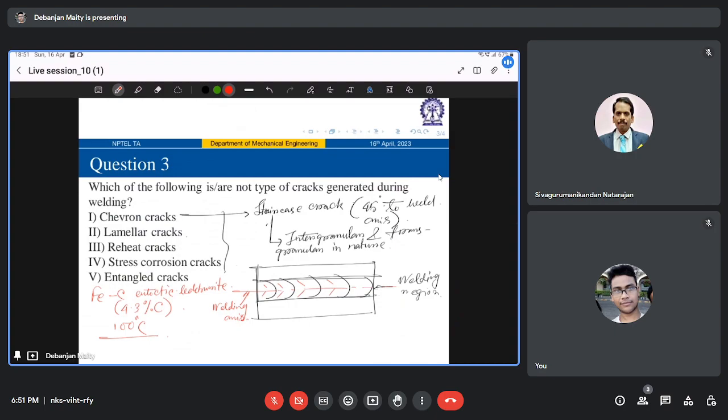They are always seen along the grain boundaries, where many second phase particles precipitate preferentially and become constitutionally liquid, and those can spread out to produce continuous or discontinuous grain boundary films, right? Now coming to reheat cracking, this is also called strain age cracking.